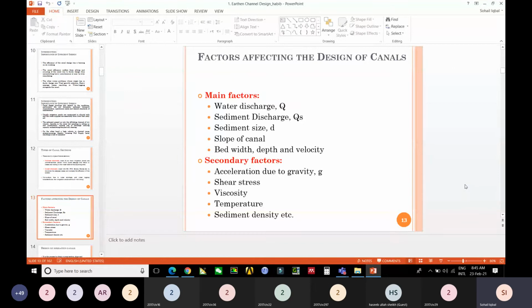If you observe, when we take a canal from the barrage or from any river, silt also collects on the barrage. So you also have a silt excluder and silt ejector provided when you are taking a canal from that river. The purpose behind the silt ejector and silt excluder is that the silt accumulation, or suspended particles, its magnitude or volume should be minimum. So we have to provide these structures, that is silt excluder and ejector.